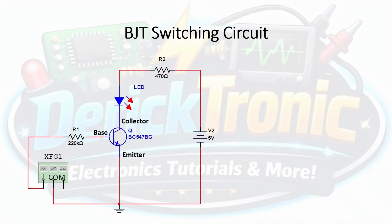Now, the function generator will be set to output an alternating square wave with a frequency of 1 Hz and an amplitude of 10 volts peak to peak.